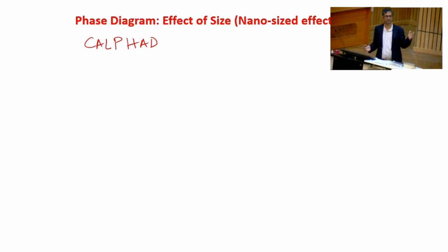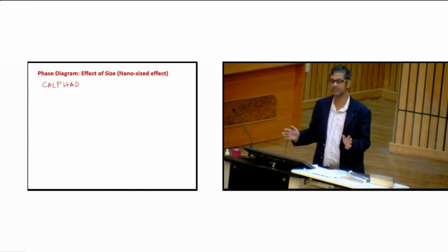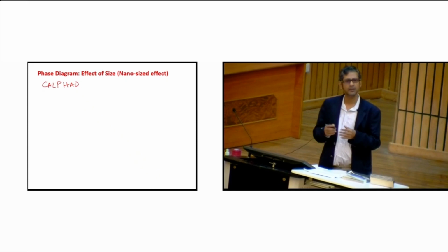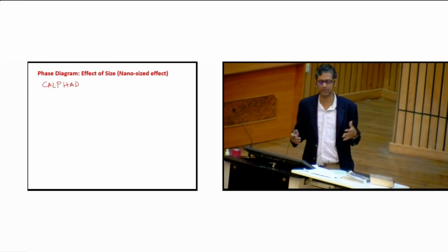You have a pressure, constant, obviously one atmosphere in metallurgical phase diagrams, temperature is not constant, and the composition variable. So, it is a multivariable minimization of free energy that is done by CALPHAD. It is a routine program which is installed in many computers. It is available in our department and many others also. It does it very simply. You do not need to write a code, but if you are interested, you can do that.